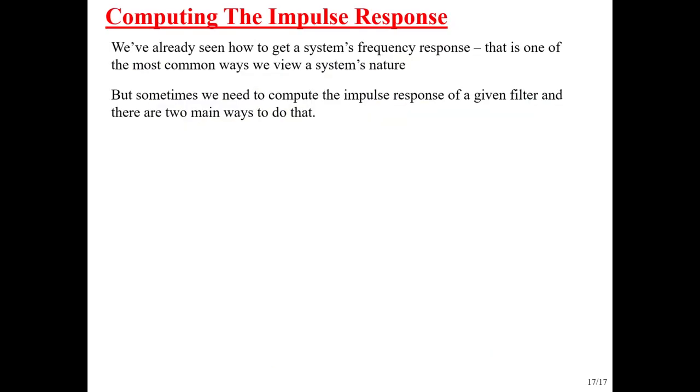And then the last thing I want to talk about is computing the impulse response. So sometimes we have a transfer function, and we could analytically find the impulse response. We could do partial fraction expansion and do the inverse Z transform and things like that. And sometimes that's useful to do, but sometimes we just have some complicated system and we have a MATLAB routine that will implement that, whether it's the filter command or the convolution command or something more complicated. And we'd like to find its impulse response, not analytically, but numerically.